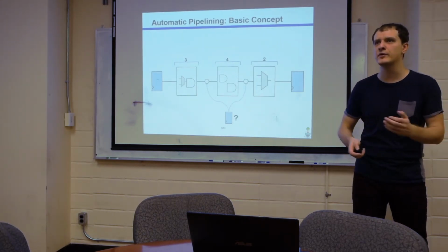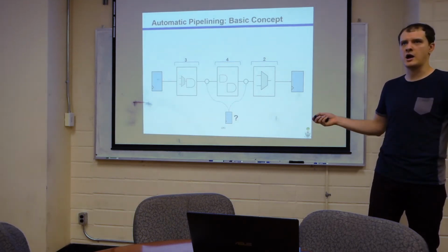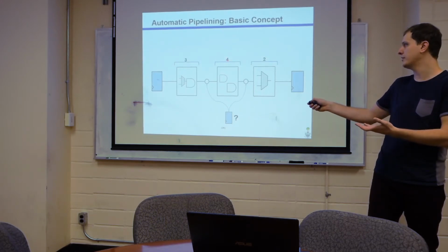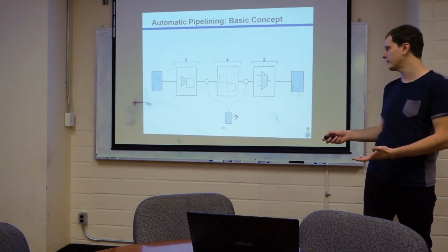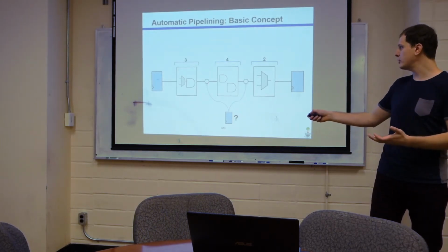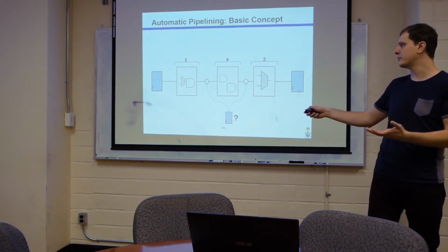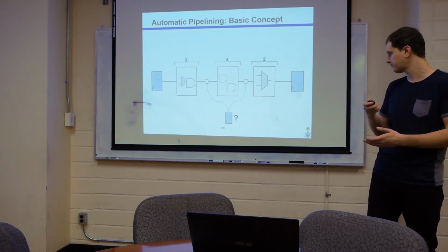So if the user asked for a maximum logic depth of 3, I'd be dead, because even though technically I could go in here and pipeline it, I can't with this model, because there's a 4 here. I would automatically fail. So those are the constraints under which I'm working. In this world, I have two locations where I could insert registers to reduce the maximum combinational logic depth, because right now it's like 9, and it could be as low as 4 if I pipeline both of these.